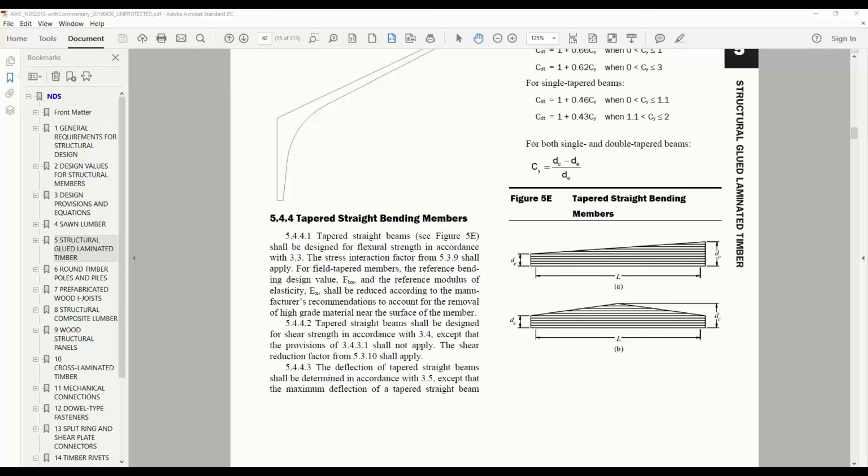So as the member shrinks and swells, if you have a steel side plate that's not going to shrink and swell with wood, this can lead to splitting around the fasteners and obviously failure associated with the capacity of the fastener. So because of that, you will want to ensure that you are detailing your connections such that you're not restraining movement with the anticipated moisture content.